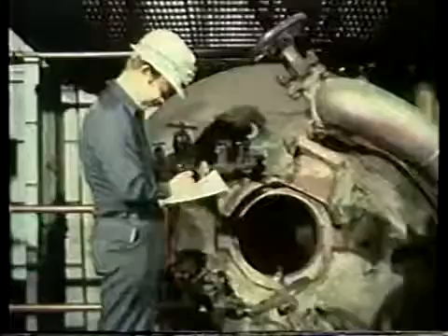Also, a wet vessel is slippery and can be dangerous. Keep track of the tools you bring into the drum or moisture separator. Make sure that none are left inside after your inspection. Left inside, a tool could cause damage to the boiler by blocking the water flow in a tube.